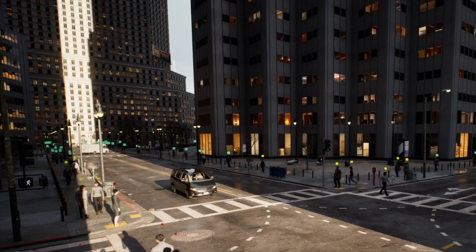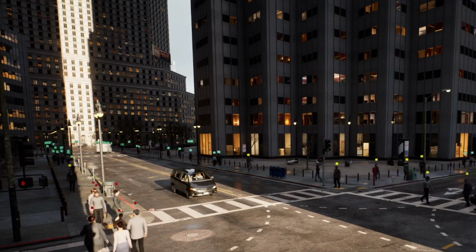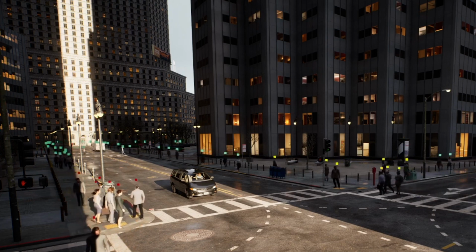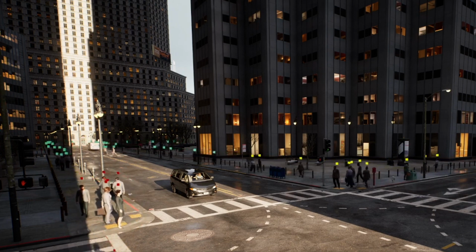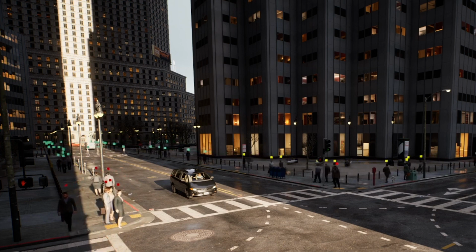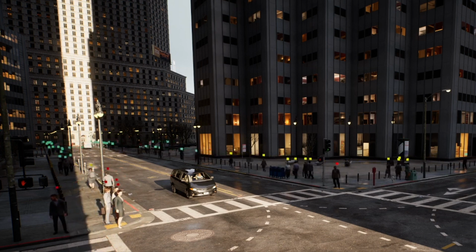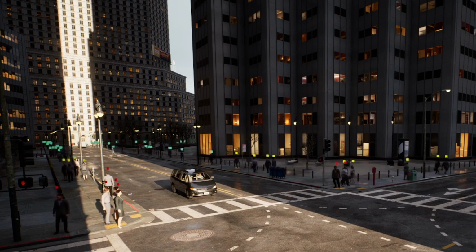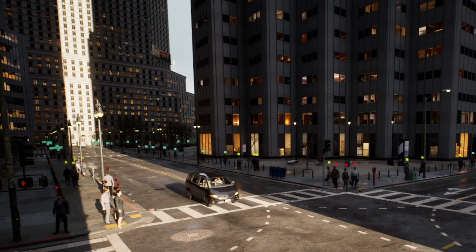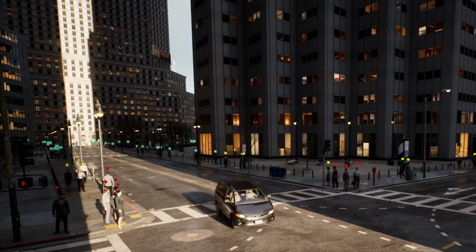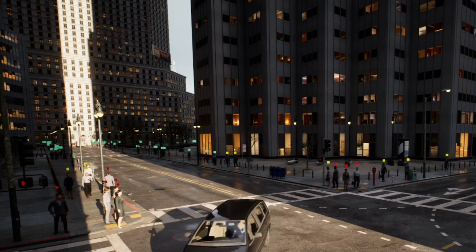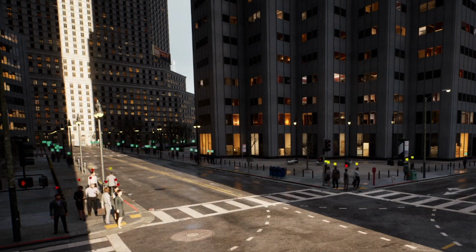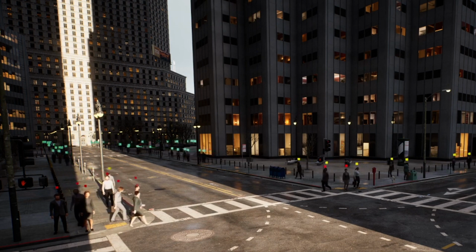As mentioned previously, the mass LOD system is key to handling a vast amount of entities, in this case, our 35,000 crowd members. By default, the framework handles 4 different LODs, along with a significant float point value between those levels. On the screen, we can see in red 10 high LOD, which are full-fledged meta-human actors with facial animation. In yellow, 20 medium LOD, also full-fledged meta-human actors with lesser facial animation. In green, up to 500 low LOD, which are lightweight vertex animated meshes. The rest are not visualized.